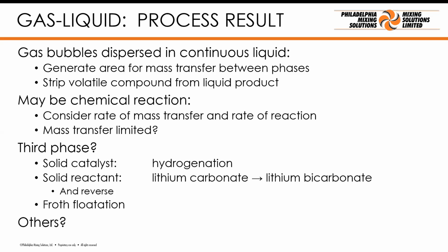Yeah, so those distributions, the D43, the D32, they represent the distribution with a single number, and the D32 has a very specific meaning, which we're going to talk about next. But if you know your distribution and you know the mass, you segregate by particle size, and you know the mass of particles in each bucket, you could do these calculations for each class of solids.